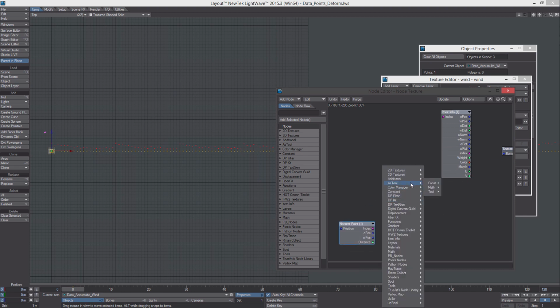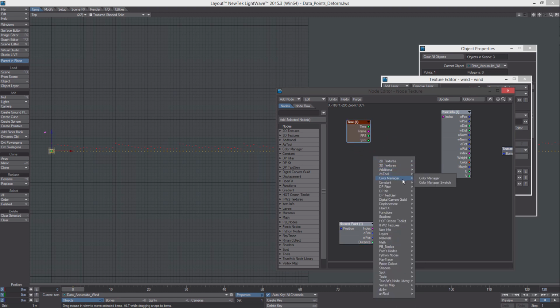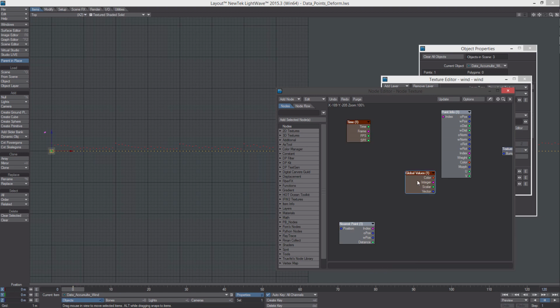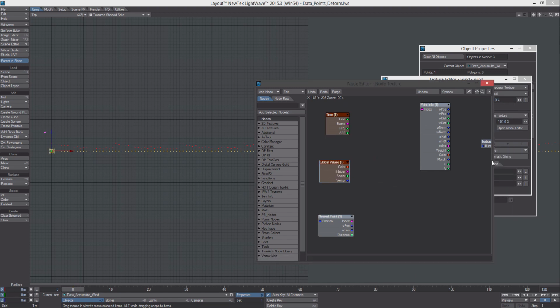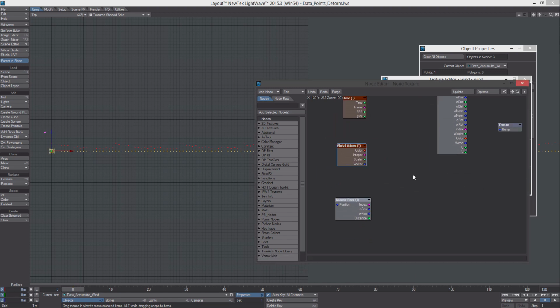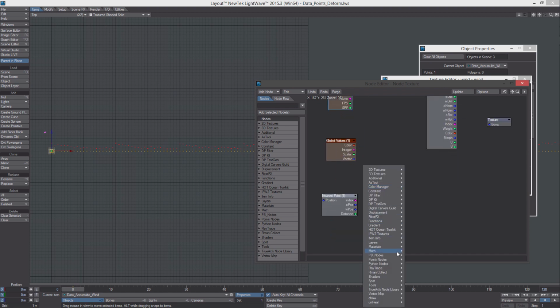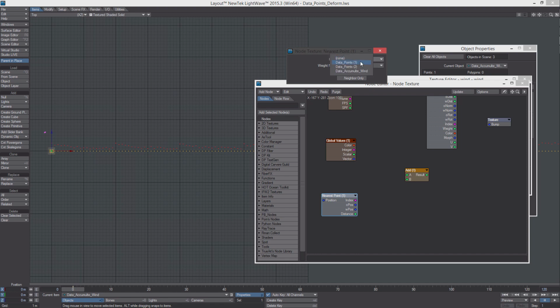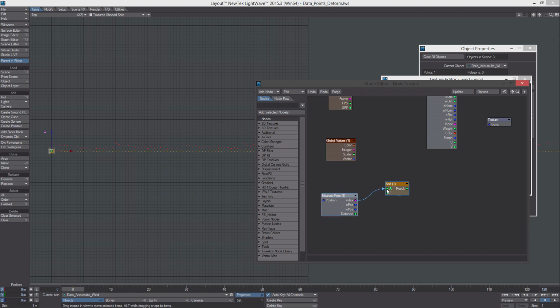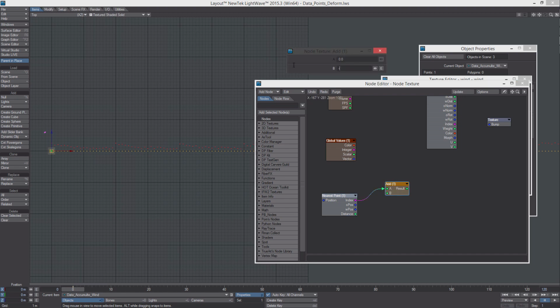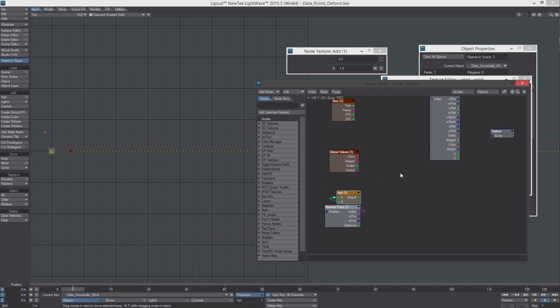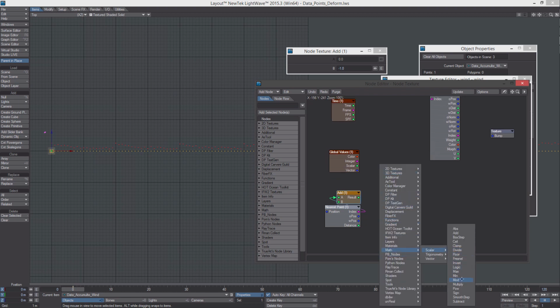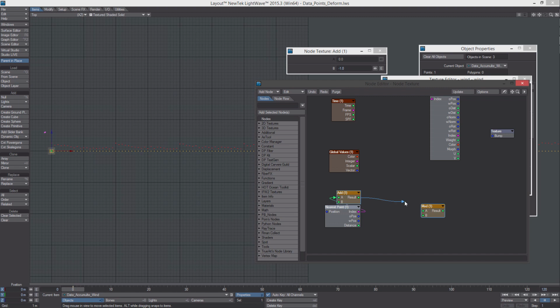and we're going to get an AS tools time, and we're going to get our constant variables, and we're going to get a math scalar add, because we've got to add one or subtract 1 from the point index because we want to start our calculations at 0. And I'm selecting the second layer for our nearest point, subtracting 1 from the index. Then we're going to mod that by 20.